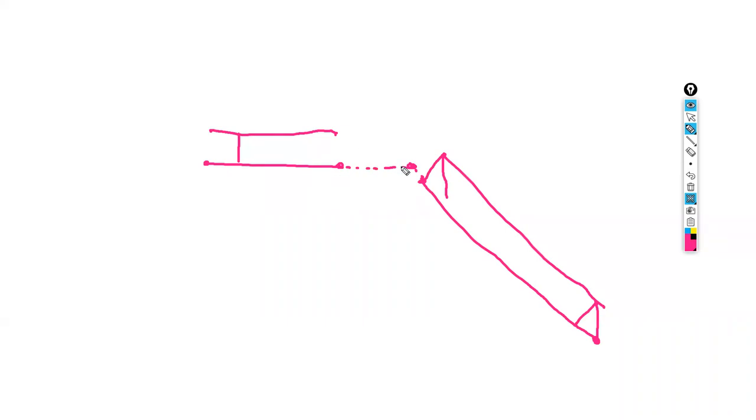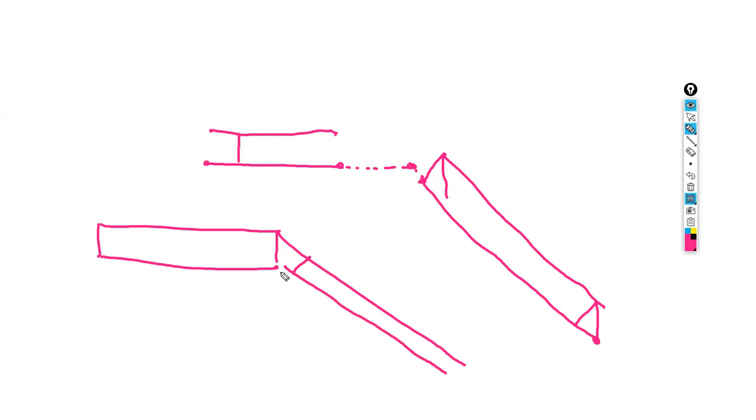So the slope is basically similar to the offset slope, in that it now uses 2 pairs of strings to calculate an intersection. And it's great for doing fill embankments or for doing subgrade ties where, for instance, you've got your pavement like this and this. You say, I want to come down here and here to find this, and I want to come out here to find this, and I want to compute this point right here, or you can find it where it projects out and finds this.